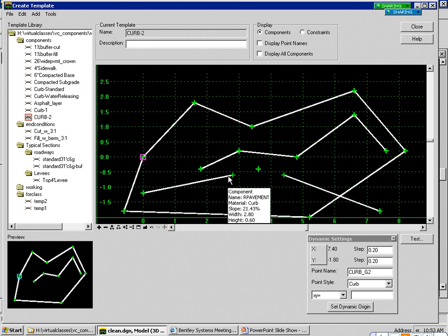When the job is actually produced, it's going to project up to here, okay, and then connect up over here. But with this null point right here, we can run what's really being built and then send a vector down over here, so we could run another line that intercepts through here from that null point. So we could have from that point to that point a vector, and take this point right here and intercept that vector, and not have to build the whole model to do it. So we could do stage construction with these null points.